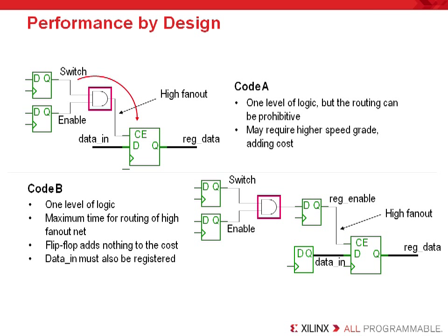In this case, the high fan-out net isn't too difficult to code for, but the source logic driving data in now needs an additional register. Otherwise, the data would be out of sync. We can't delay the control signal without similarly delaying the data by a clock edge. Since this must be built into the HDL code, it is very important that you keep in mind from the beginning that these kinds of paths are probably going to need this added register. Otherwise, you may be rebuilding your design sooner than you might like.